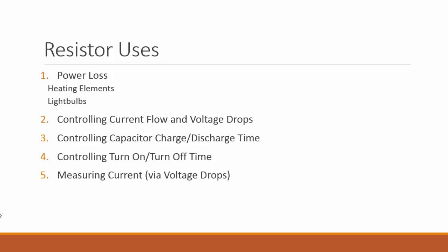So you want to use a small resistor. On the other hand, if you want, for example, to have a long, drawn-out dump of energy, for example, if you unplug something and you want to have a capacitor give you energy slowly, in a fairly constant amount over a long time period, to take over for whatever energy you lost when you unplugged the device, then you would want a large resistance to increase the time constant. Or if it's important that your current turn off or on over a short or long time period, you can use resistance to change that significantly.